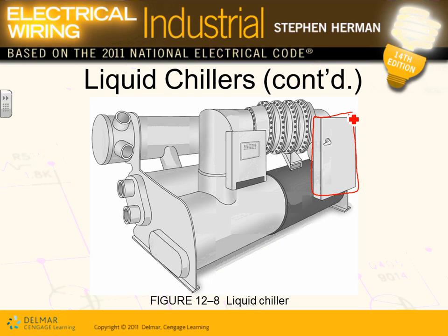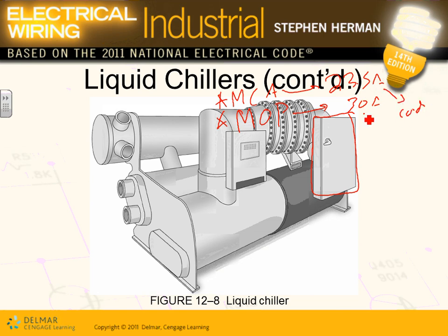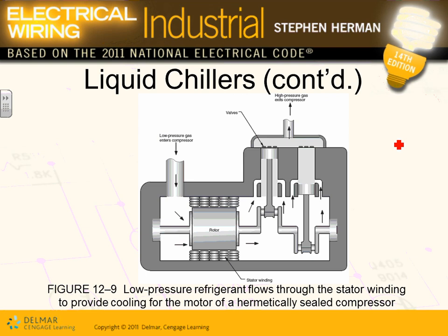So when you size this one, Anna, you need two things. You need the minimum circuit capacity and the maximum overcurrent protection device. Say this one will be 23.5 amps and this one will be 30 amps. You go size your conductor, this will be the conductor, this will be the fuse or circuit breaker. Done. So that's your liquid chiller.